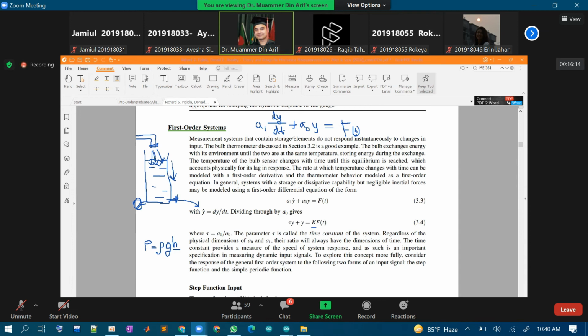That will show up as a rate of change of pressure when we do the reading, and initially definitely there will be a static pressure part. So that is how the first order systems play out. And now you can understand all kinds of places where you can be using this in engineering, in mechanical. It can be a water tank, it can be some boiler, it can be some chemical treatment plant, it can be even your fuel tank in your vehicle. You're burning fuel and it's going down, you're reading it, there is a pressure gauge there, right? Like this. So those are some of the things that you can think of as first order.